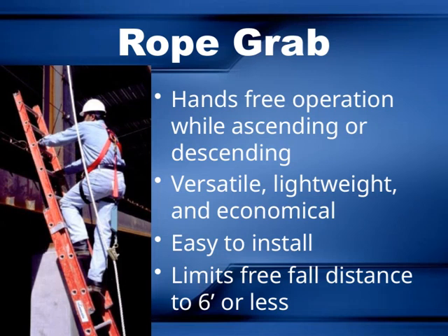Now, let's talk about the hands-free operation while ascending or descending. This feature allows you to move safely and efficiently without needing to hold onto the lanyard constantly. It's designed for convenience and safety, making your work easier. The system is versatile, lightweight, and economical, which means it can be used in various situations without adding extra bulk or cost. Plus, it's easy to install, so setting it up won't slow down your workflow. One of the key safety features is that it limits the free fall distance to 6 feet or less.